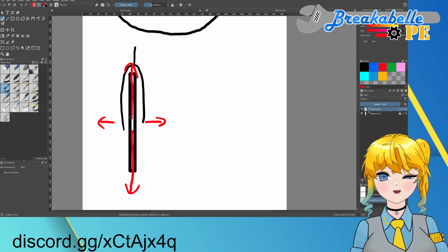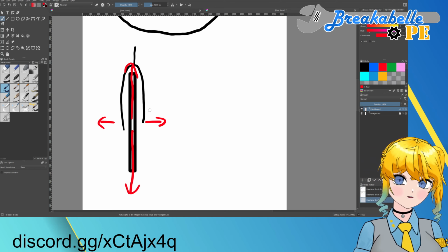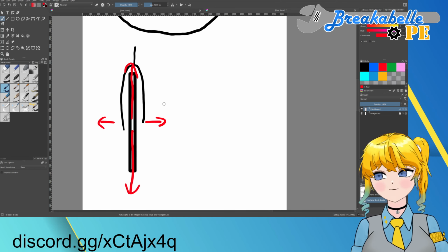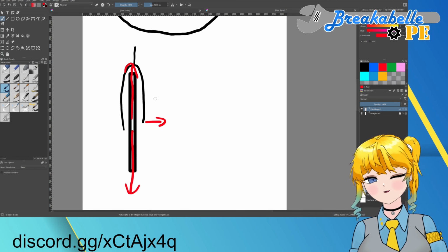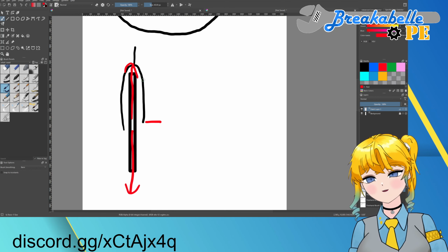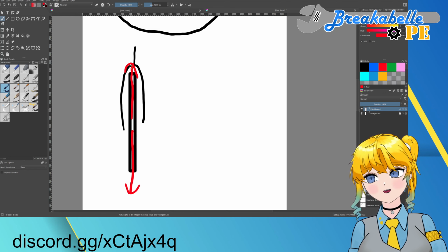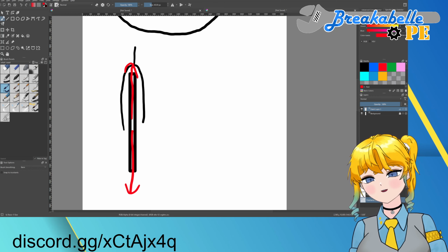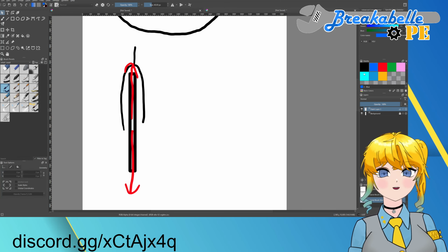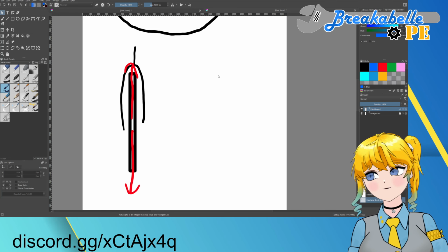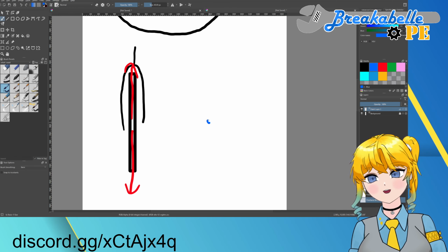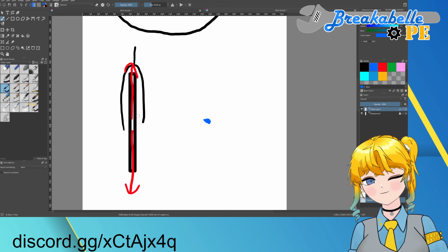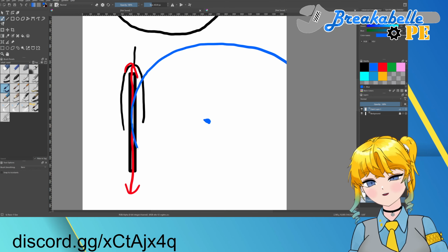So in order for it to go that way, there has to be slip. And of course the wheels don't want to do that. We don't like slip, right? So wheels are always trying to go one direction or along one axis. In this case, it's up and down. That is always going to be perpendicular to the point of turning, because if you're turning about a point, that means you have to be going along a path in a circle around that point.